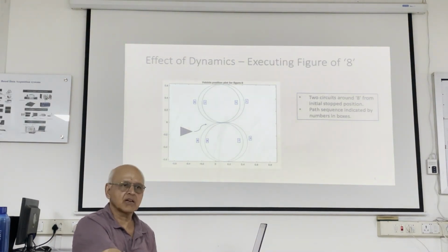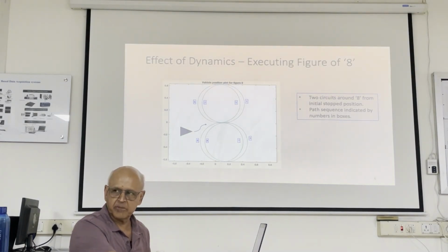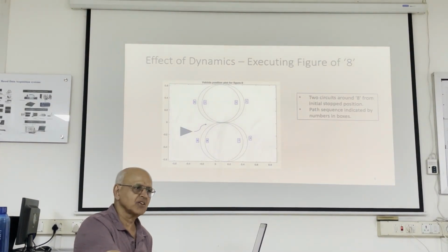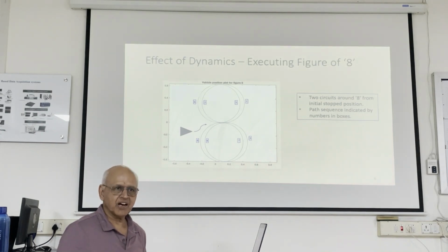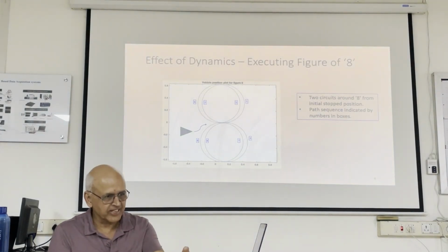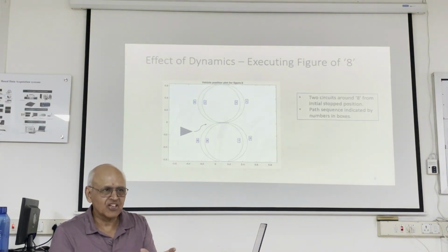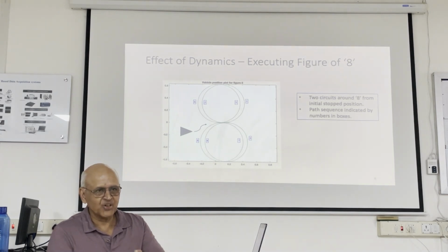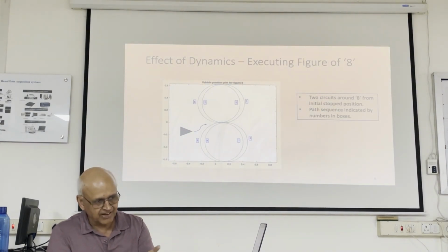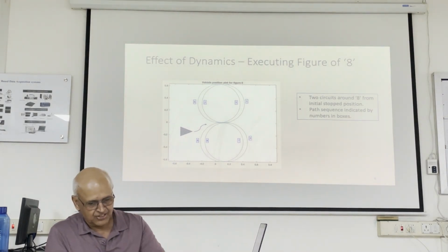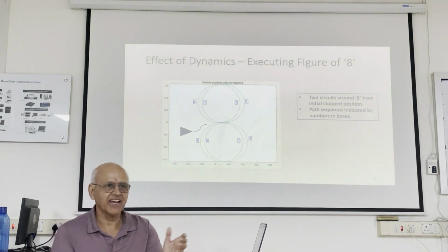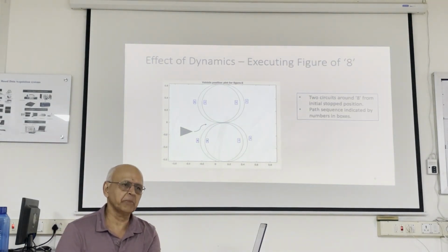So this is a good indication of dynamics, a simple experiment to show that. So why would you care? It's because when you're telling it V omega, and you think this should go through that gap, realize the delay, because you have to compensate for the delay. You can't just say, I have a circle here, that circle geometrically penetrates the gap, so I'm okay. Because there is a delay. You don't get the circle immediately.